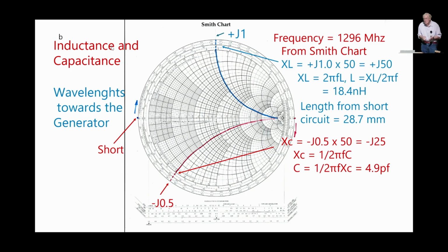And those of you that had a look in solid state amplifiers, you'll often see just a line that's sort of hanging off the main transmission line, and that could be a trap, but it also could be a capacitance or inductance. You can actually trim the length of those and vary the amount of capacitance. And you can see you were talking about pretty small capacitances there, but you can accurately put a transmission line on a piece of printed circuit board to a fair degree of accuracy. So yeah, we use transmission lines as capacitors and inductors.